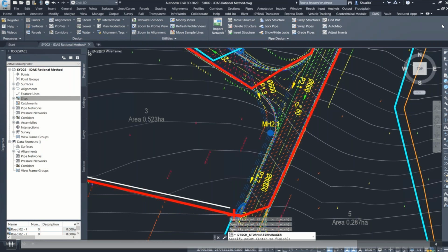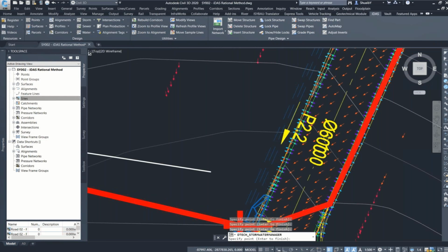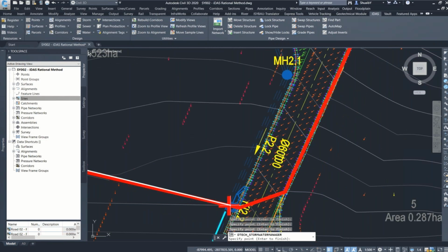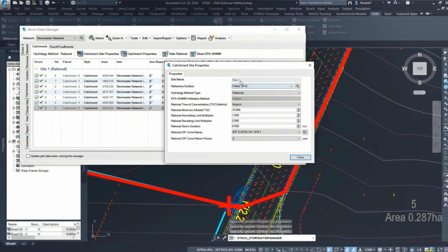Okay, so I think we've got all of the flow paths done and dusted. We've got all of the catchments done. Now we have also inputted the data, because when we did the flow paths, everything populated, as you saw. Okay, so now let's just finish this off very quickly. Click here and it's going to pick up the location. So that X is the draining point, of course. I'm sure you probably put that together by now.